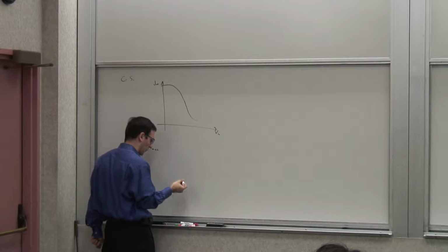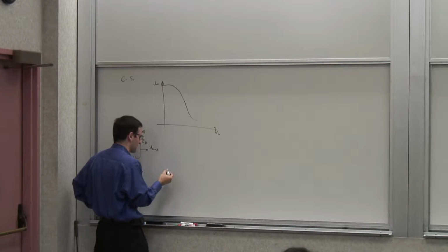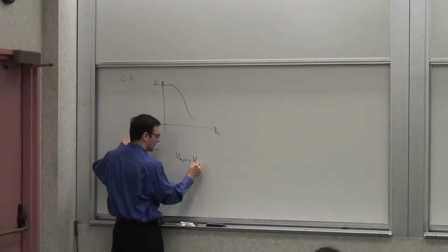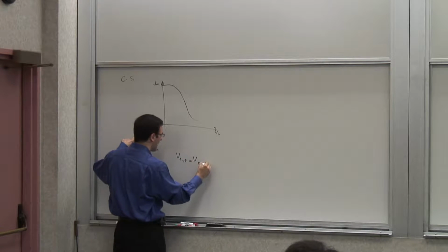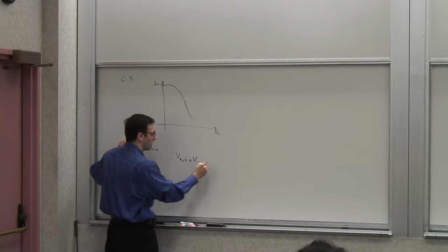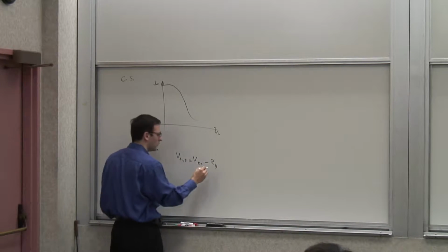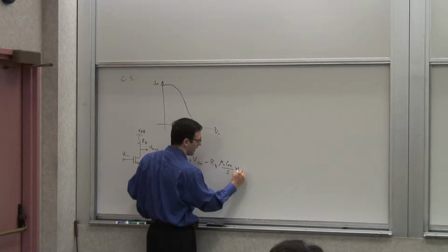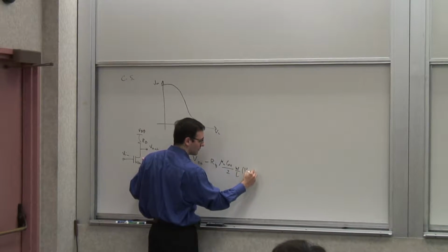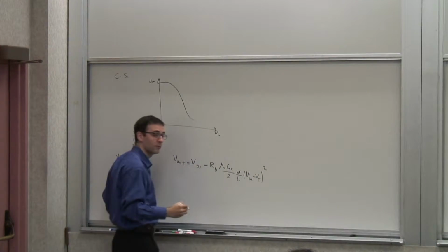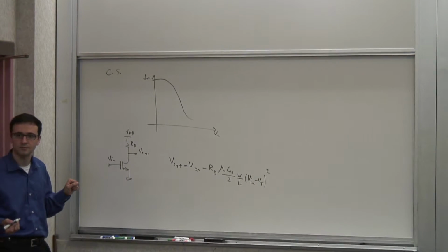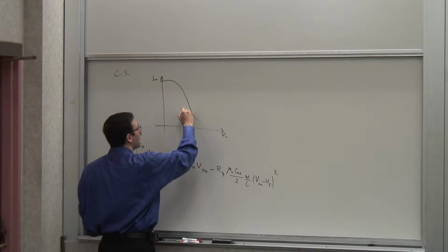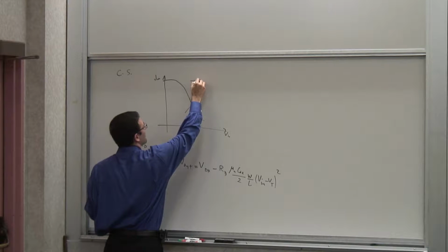And then when we wrote down the large signal transfer function, we basically said V out is simply VDD, this voltage, minus the voltage drop across the resistor, which is RD ID. And ID was mu n C ox over 2 W over L, (VGS, which is V in, minus Vt) squared for a non-velocity saturated device. And as you can see, this is basically the input-output transfer characteristic for the pinch-off region, for as long as you remain in the pinch-off region.